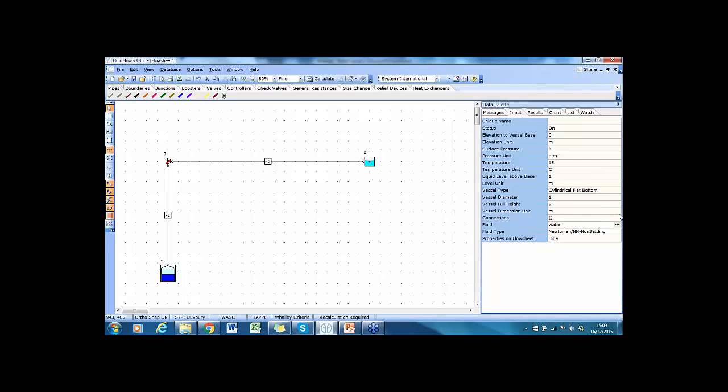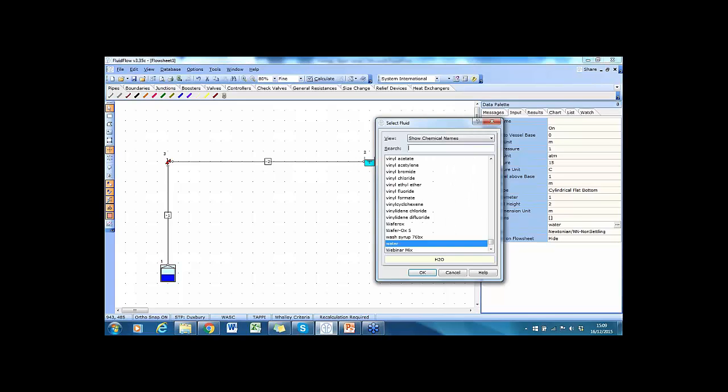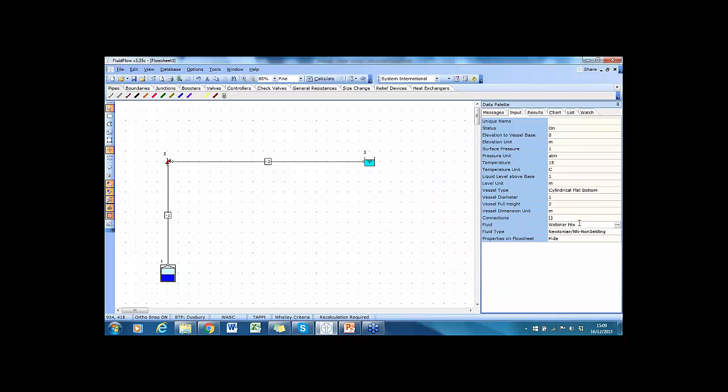Okay, so I've now assigned this fluid to the database, and now I needed to assign it to the model. So very quickly, assign the fluid to the model, and now I can set about defining my design conditions. So the inlet pressure was 97.2 psi absolute. So I'll just scroll through my pressure units. Temperature was 348 Kelvin. Okay, I can just leave some of these default parameters because they're not so critical.